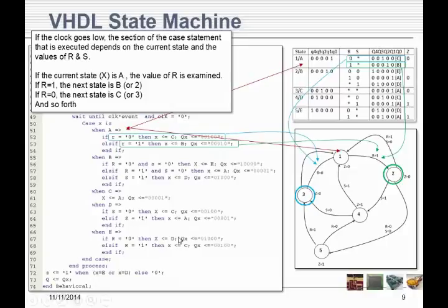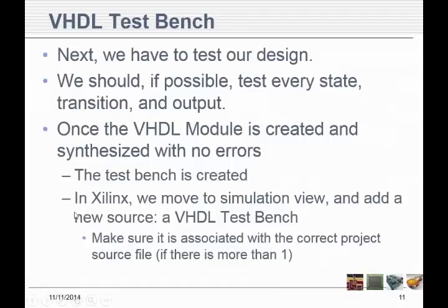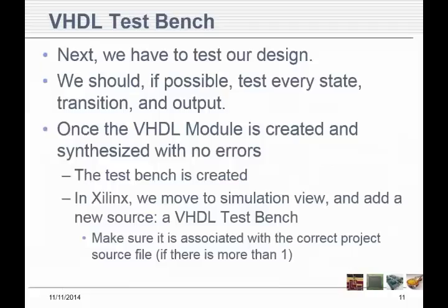Okay, so I got all those, and we go to the next one. It's finally after I come out of the process that I assign my output its value and my flip-flops their output value. And now I'm going to let Xilinx come up with what's going to be best, whether JK, T, D, whatever kind of flip-flop it wants to come up with.